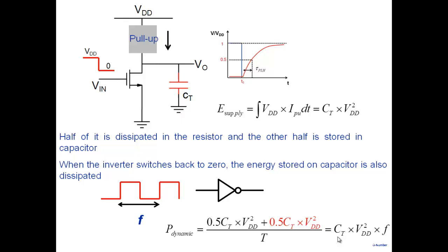So you can clearly see, if we were talking about a microprocessor, why can't I increase the clock speed of the microprocessor? Well, if you increase the clock speed of a microprocessor and you have a 100 million transistor circuit, imagine how many nodes are there in that circuit. Now, every node will, of course, not switch. Some nodes will switch, some may not. So a fraction of nodes will switch. All those switching of the nodes, you can imagine how much will be the power dissipation. So the bulk of power dissipation in all these digital circuits comes from switching of the nodes. You have to switch the node on, off, 0 to 1, 1 to 0, 0 to 1, 1 to 0. All that power is coming from that.